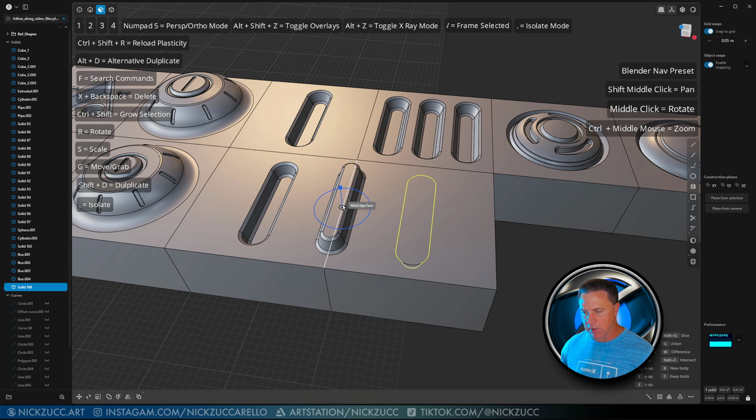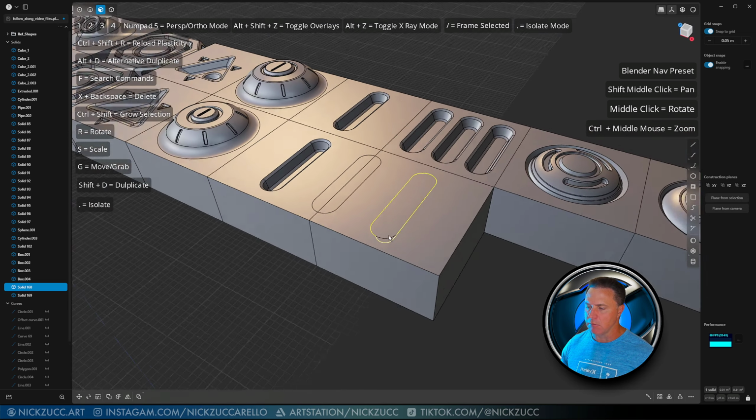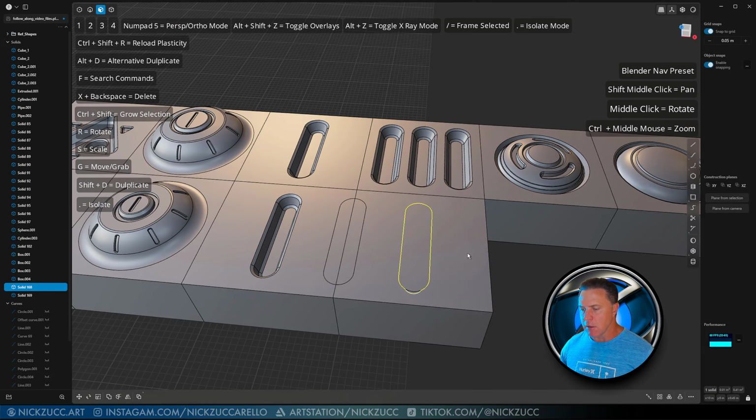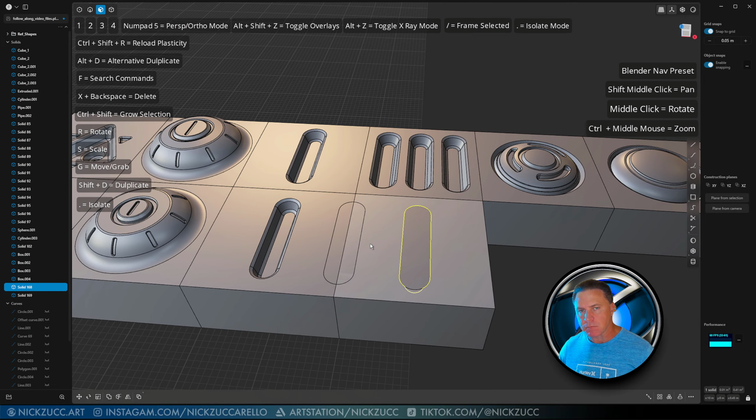So let's say we want to flip it that way, you can tap F to flip it like that. You could actually scale it as well. It says on if you click S for scale, so that'll scale this thing in and out, and I actually want to flip that still. So I'm just going to create one here, right click, and if I hit escape I can get out of that. So you could do multiple placements of things on the surfaces with that workflow right there.